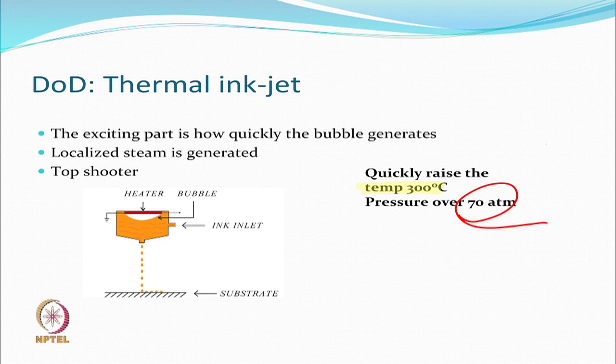So, bubble jet printers in some way are thermal inkjet printers, where a bubble is created by heating. But obviously, you have control over when to create a bubble. If you pass the current, then there is a heater which will get heated. If you do not pass it, then it will not do that. So, that control is with you. How much energy you generate, and how long you pass the current, will also determine the outcome. The resistance is like a heater. So, you can do that. Very interesting technology this is.